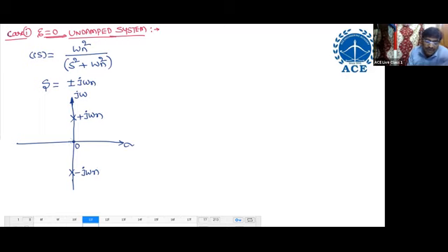Now find the time constant. Tau equal to minus 1 by the real part of the pole, which is 0. So that equals minus infinity. But time constant should not be negative, so that means infinity. The undamped system has time constant infinity. Imaginary part gives the frequency of oscillation, already covered. What is that? Omega n, radians per second.